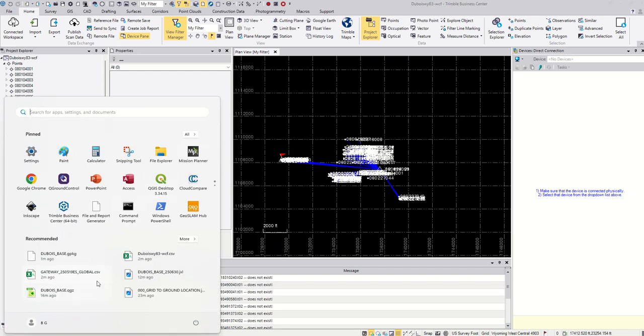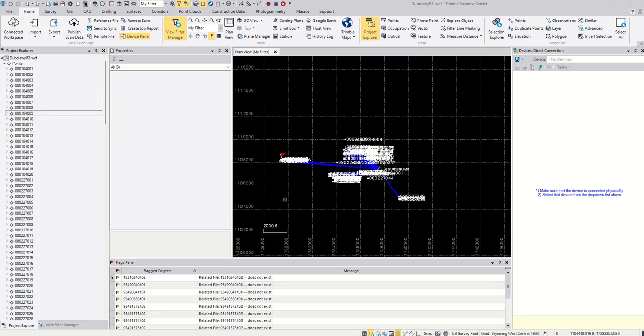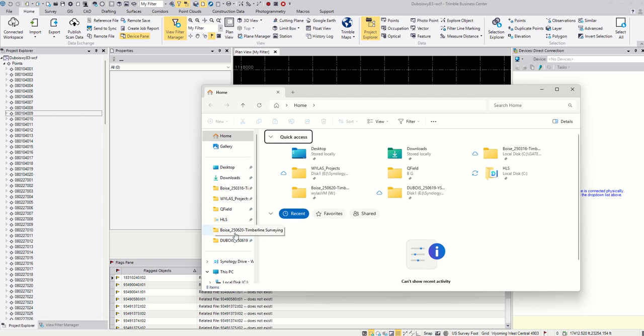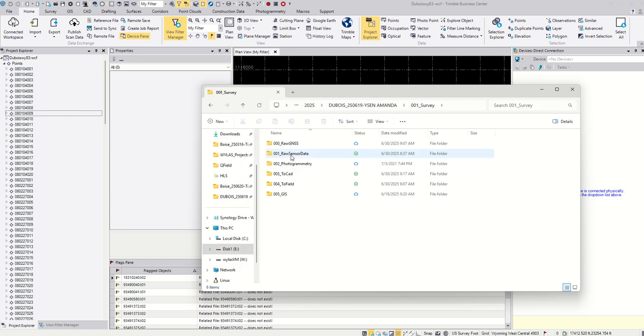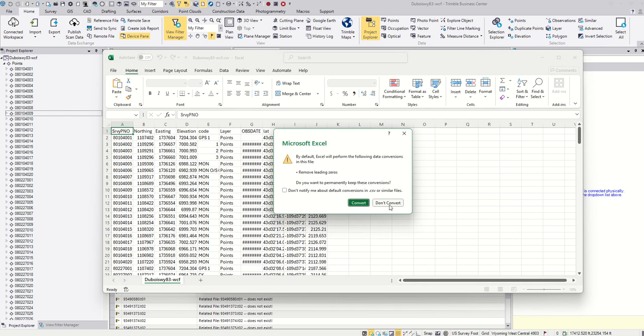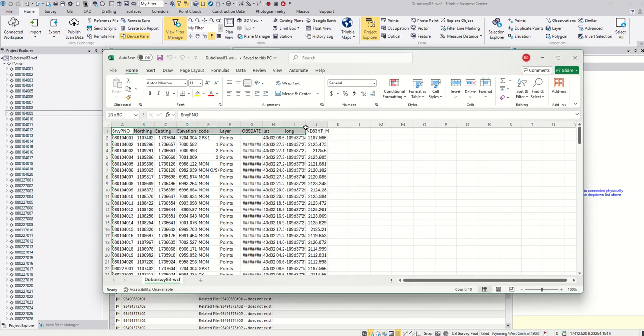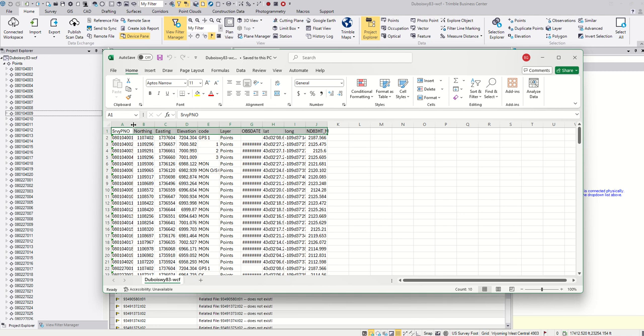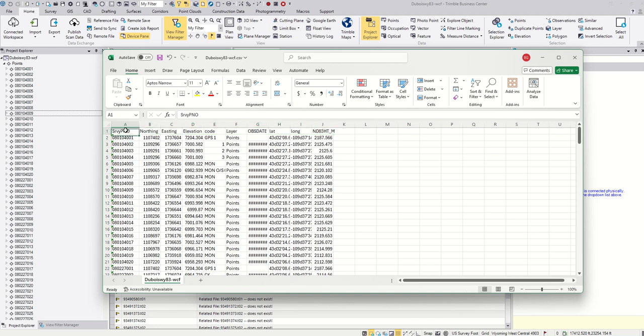But then it's important that you change the header of your CSV that you output. So in this, you're going to go ahead and change the name of the file here, or the header, so that it is not going to be too long for Civil 3D. Civil 3D is very picky on how many character lengths that it will accept in fields.